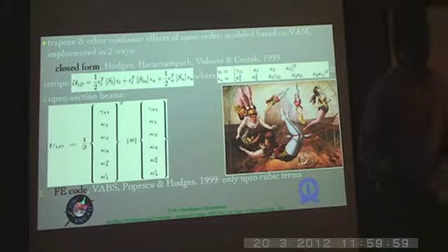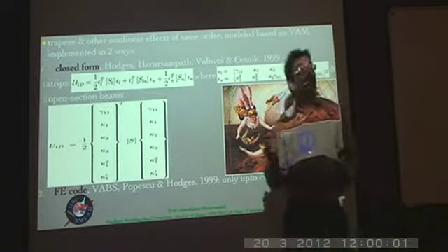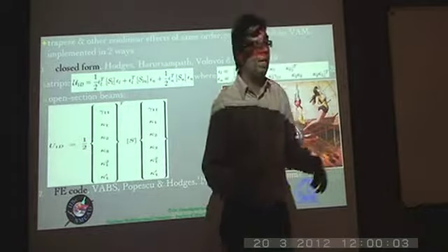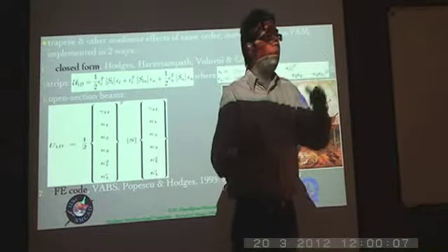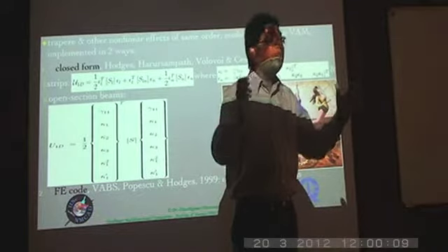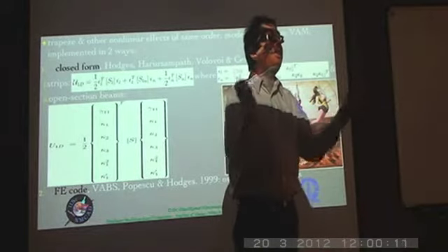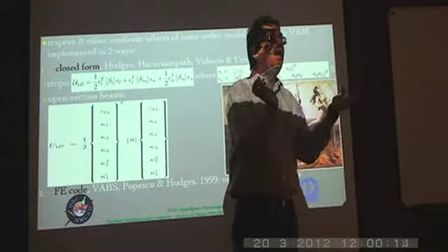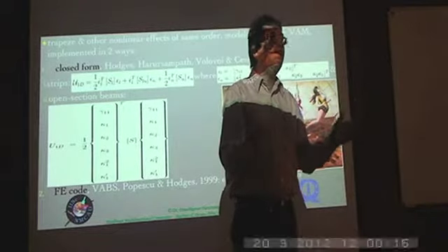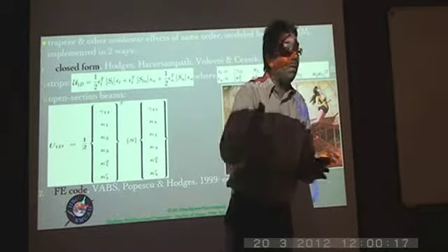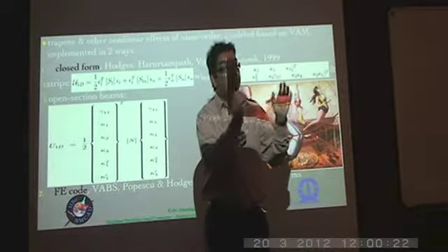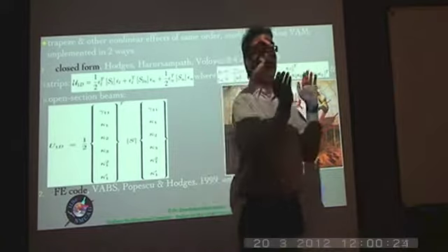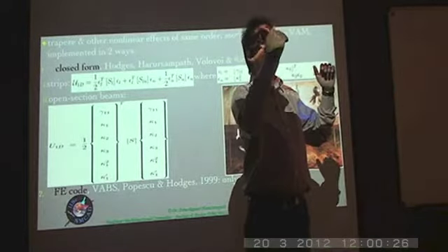See, non-linearity happens if and only if some of the deformations are very large. Once you increase the thickness of a plate or a beam, it becomes stiffer, and therefore the curvatures that it can have before failure are fairly small. So we will come into the actual mathematics of it shortly, but basically you see that the strain itself is proportional to the curvature times the distance from the neutral axis.